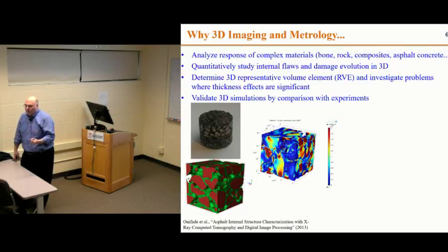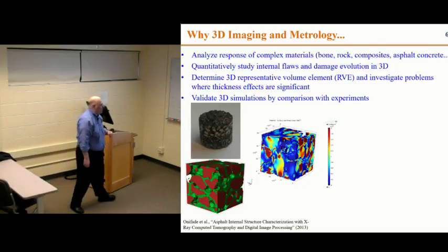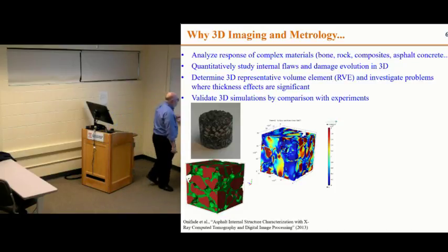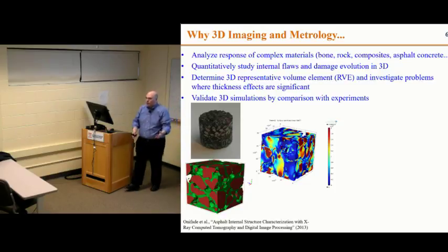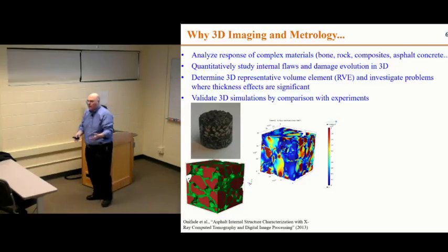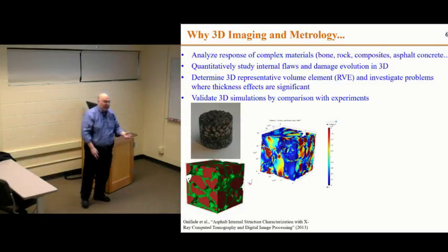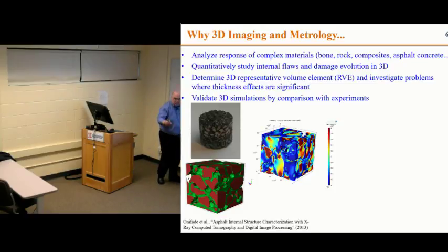The way that we've dealt with that on the 2D side is by increasing magnification considerably. This is kind of like what we did on the surface to look at the damaged process zone in the asphalt concrete. So you would increase magnification and say, this area is primarily green, meaning matrix. If I look into here, I can analyze this and get some strain field, but it's going to be in isolation. I won't know what will be happening in the rest of the object unless you do some kind of multi-scale measurement or some kind of tiling or stitching, and that's what we do in 2D. That's precisely the kind of thing that we've done.